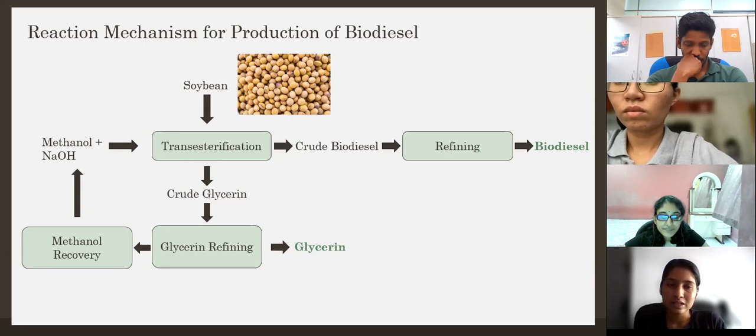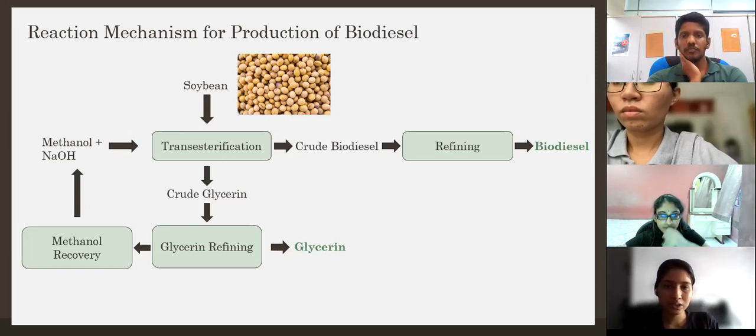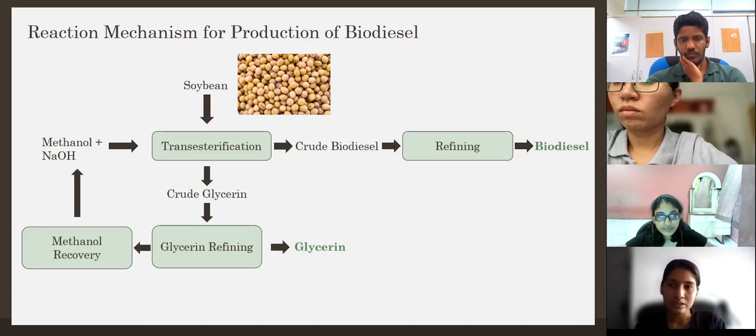Then the transesterification takes place, where the pre-treated triglycerides are reacted with methanol to form the raw methyl ester and glycerol. There are 2 basic steps: first, the reaction process, followed by the separation of the methyl ester and glycerol streams. In most technologies, these 2 steps are undertaken twice to push the transesterification closer to completion by reducing the concentration of glycerol in the second stage.